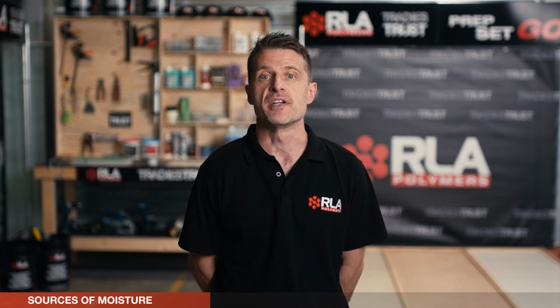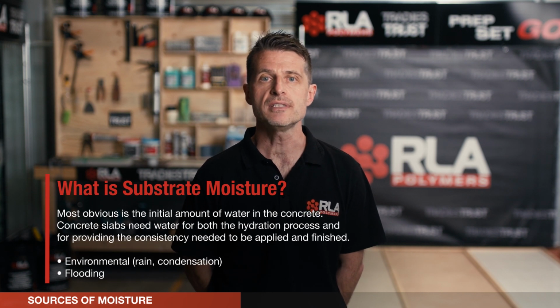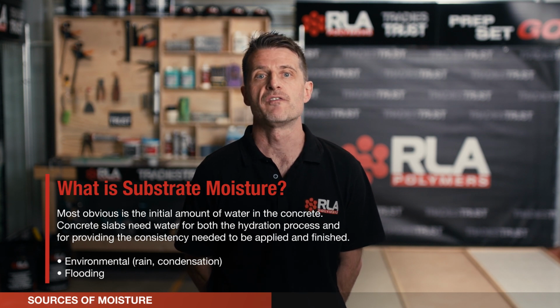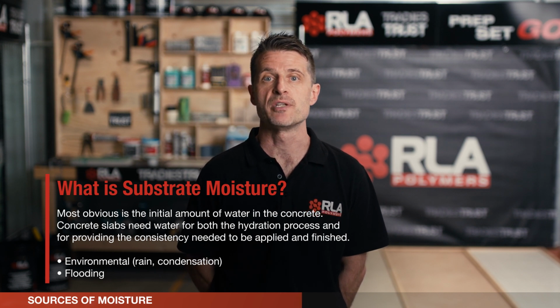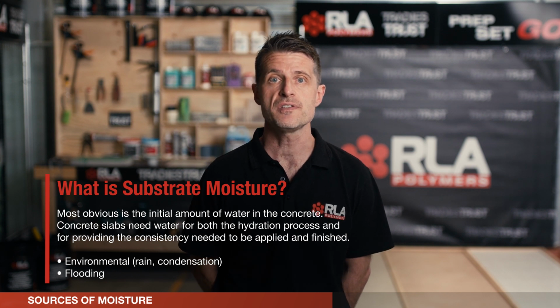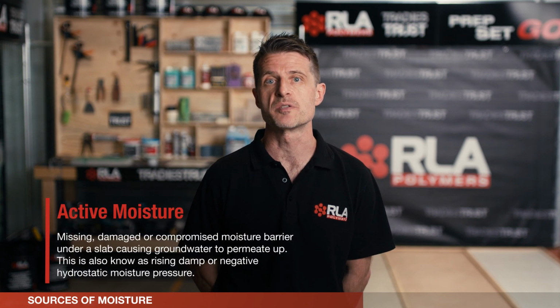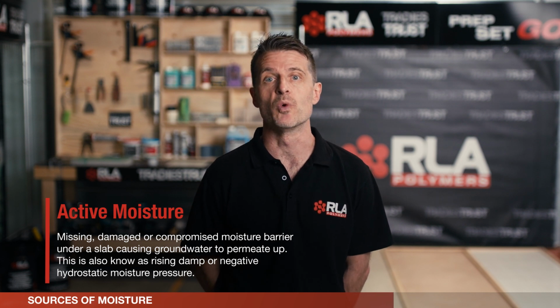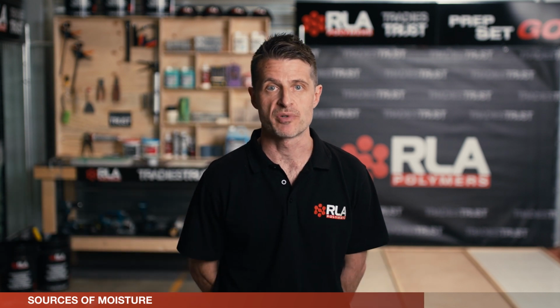Now, let's look at the various moisture sources in a concrete substrate. The most obvious is the initial amount of water in concrete, and concrete slabs need water both for the hydration process and for providing the necessary consistency to be applied and finished. Environmental considerations are things like rain, condensation, and dew on the surface. Could also be down to flooding. But then there's also active moisture, and this is often caused by missing, damaged or compromised moisture barriers under slabs, and this causes groundwater to permeate up. It's also known as rising damp or negative hydrostatic moisture pressure.